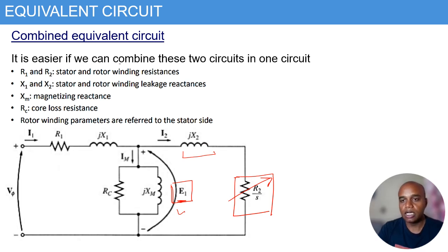I hope with this video two things are clear: one is how to model a physical thing into a mathematical expression, and the second, which is a very famous interview question, is why the rotor resistance becomes a function of my slip. It is just to represent my rotating rotor as a fixed, stationary rotor. Okay, thank you.